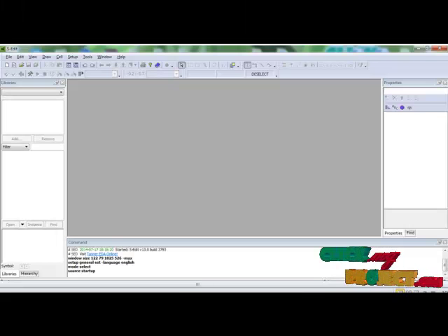Now the tool. In this tool, basically it has a lot of sub-devices. That means we have S-Edit, W-Edit, L-Edit. Like this, we have separate layouts for waveform design and for circuit design. Similarly, we have separate windows for designing separate parameters. So our CMOS design is performed in S-Edit, and the performed design produces the output in W-Edit.